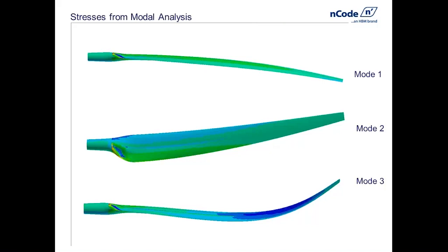And so what we're interested in is seeing from each one of these modal stresses their influence on the strain gauges, basically the output response to the strain gauges. So our input is these modal stresses. We bring it into the virtual strain gauge. We have virtual strain gauges applied at every one of the actual gauge locations.